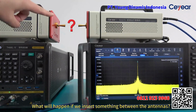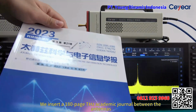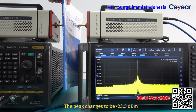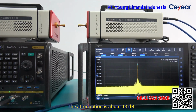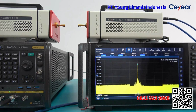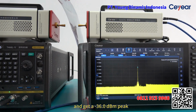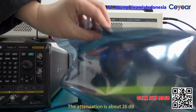What will happen if we insert something between the antennas? We insert a 180-page Terahertz academic journal between the antennas. The peak changes to minus 23.5 dBm. The attenuation is about 13 dB. We insert an anti-static packing bag and get a minus 36 dBm peak. The attenuation is about 26 dB.